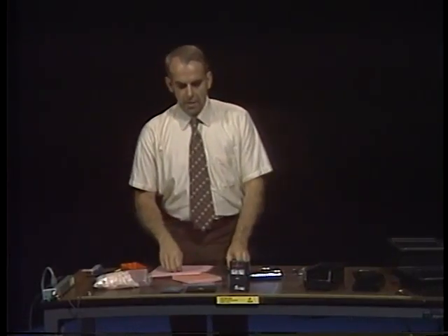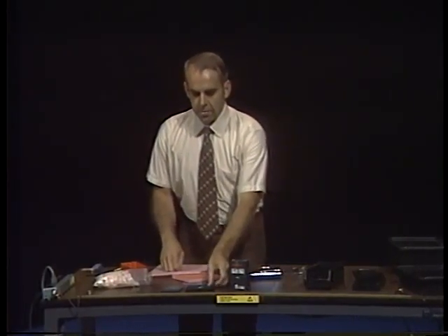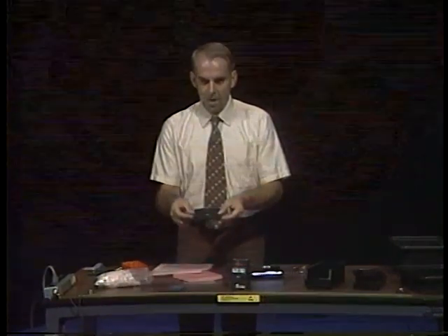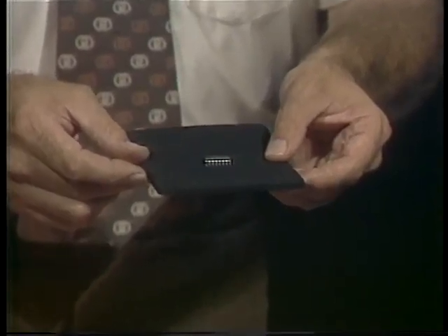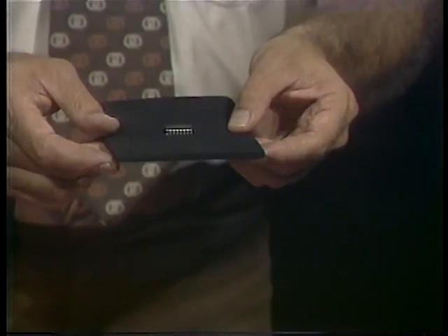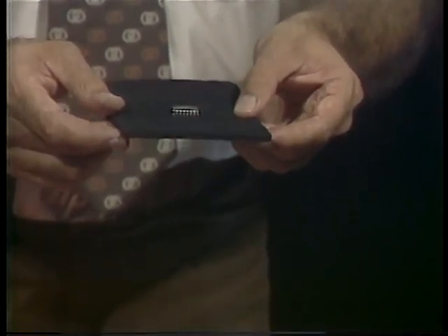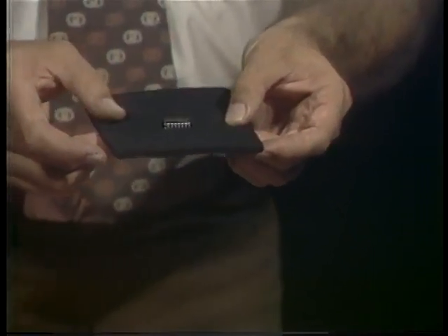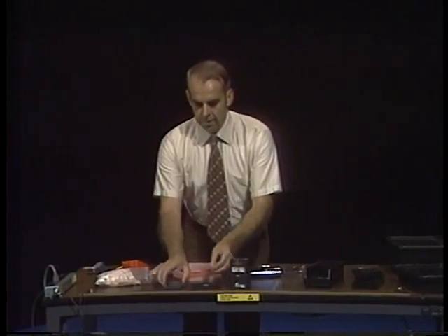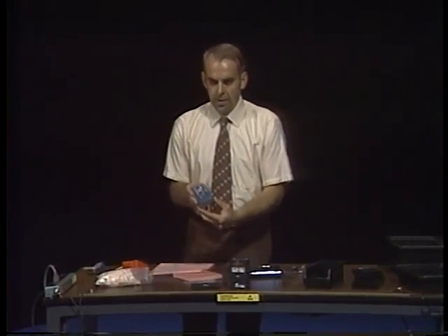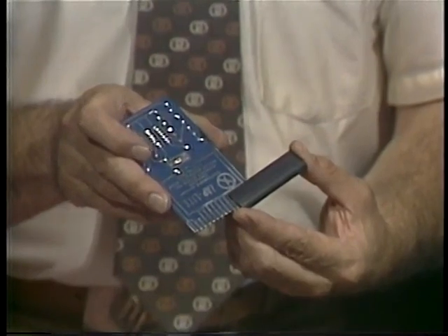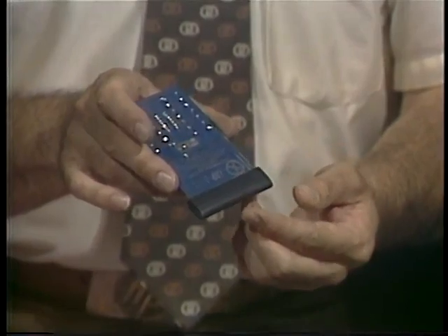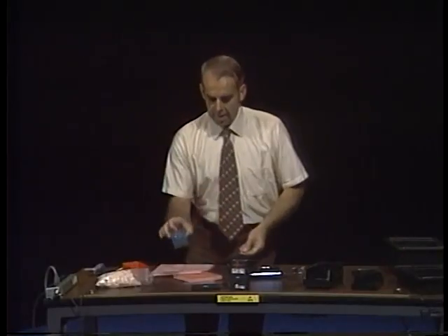The third element in the anti-static campaign is to short all the leads of devices together where possible. Here's an example of an integrated circuit which is inserted in black conductive foam so that all 14 leads are effectively shorted together. This device is very well protected, providing only that the foam does not contain any contaminants which might cause corrosion. Similarly, you can protect a printed circuit edge connector by shorting the pins of it together with this carbon-loaded rubber clip. Now all the pins are shorted and the board is well protected against static.